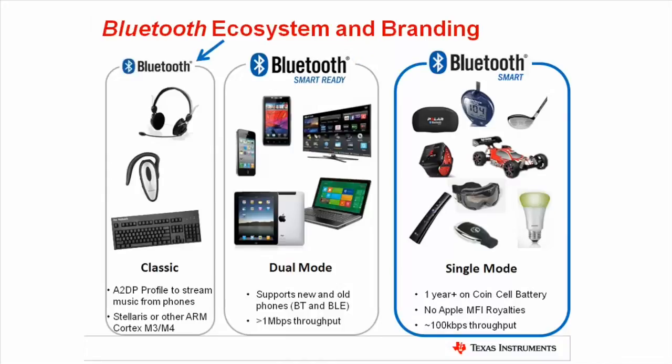Prior to Bluetooth 4.0, the accessories, products, and devices connecting to phones or computers have mostly been limited to audio headsets or HID devices like mice and keyboards. Additionally, streaming audio applications continue to use classic Bluetooth technology for those larger packet sizes and higher data rate applications, as Bluetooth Low Energy is not suitable.